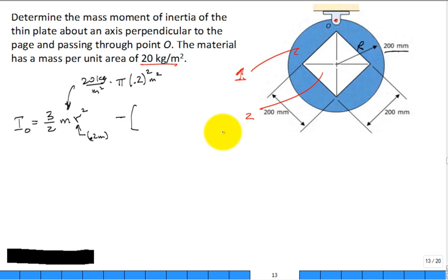All right, well, that square hole, I'm going to have to use the parallel axis theorem. I'll put it through this point. That's a centroid of my square. Do they give it to you anywhere on our sheet for the square? You just find it. What is the value for that thin square plate? Is it going to be the 1/12 the mass of the whole of the square plate times 0.2 squared plus 0.2 squared. I know A and B are the same in the equation, and you could simplify a little bit, but that'll work.